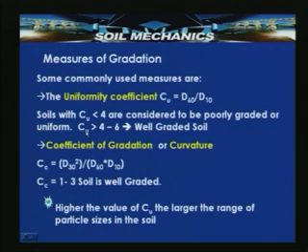Uniformly graded means the particles have identical sizes. For example, for desert sands, Cu will be approximately equal to 1.